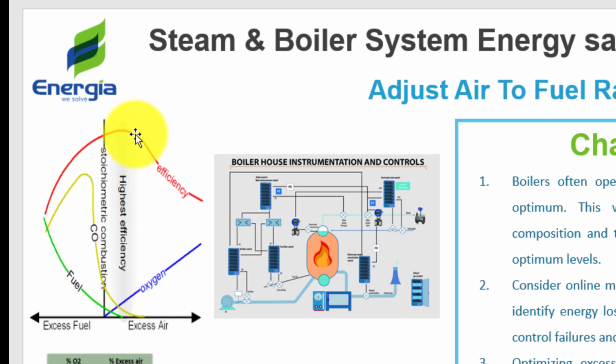Typically, you can say, okay, what is the optimum range? With the optimum range, we want to stay here. And if we consider natural gas boilers, which are the most used now in industry, we're talking about the range between 1 to 3% excess oxygen, which is represented by 5 to 15% excess air. This is the optimum range, starting from here to the peak.